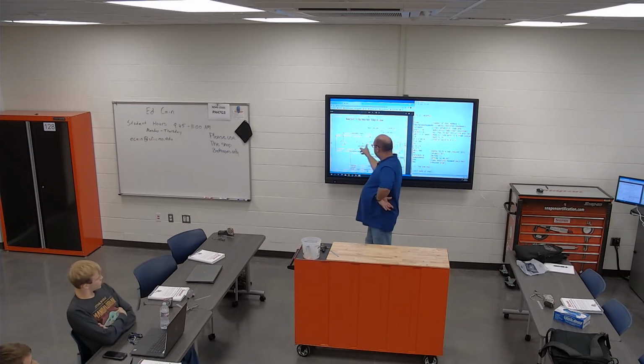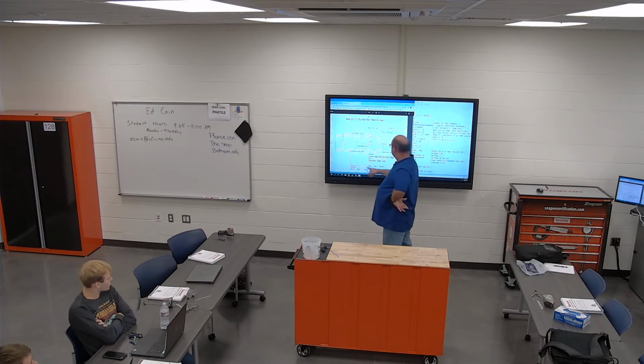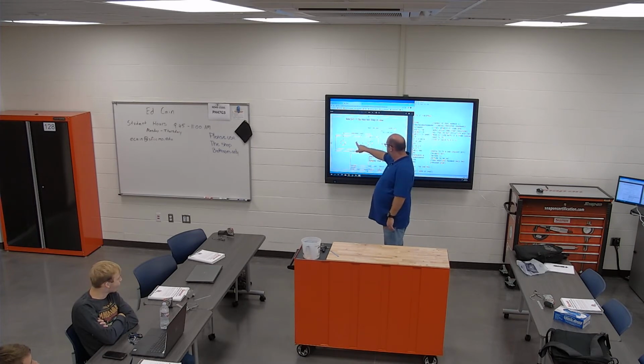So it's going to start here, it's going to go all the way off. The thing that you use to figure out this 5.5 is the distance from here to here plus at least half of your cutter, so that you don't start your shell mill on top like this. You want your shell mill over here when you start.